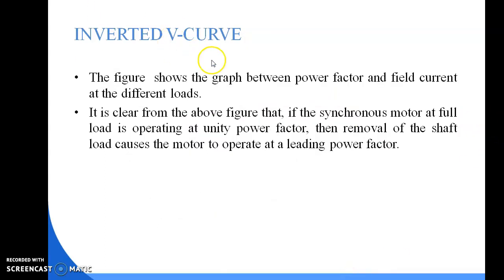So, inverted V curves. The figure shows the graph between power factor and field current at different loads, which we have already discussed. It is clear from the figure that if the synchronous motor at full load is operating at unity power factor, then removal of the shaft load causes the motor to operate at a leading power factor.